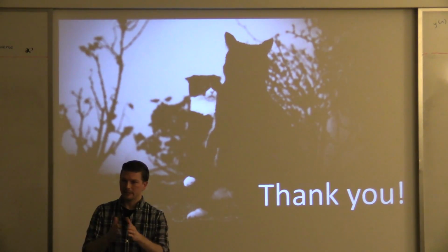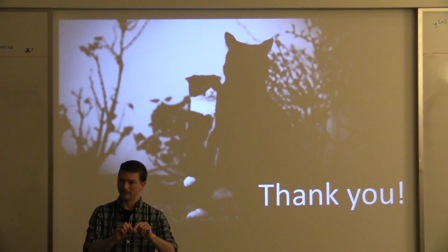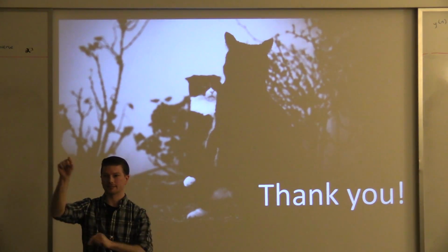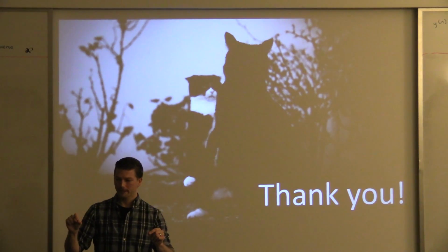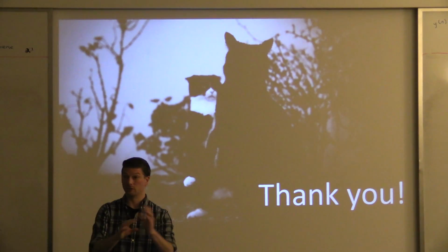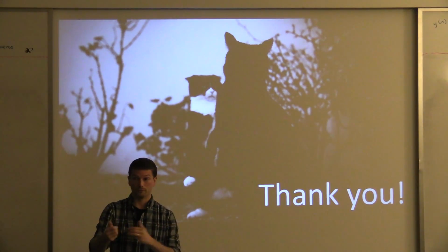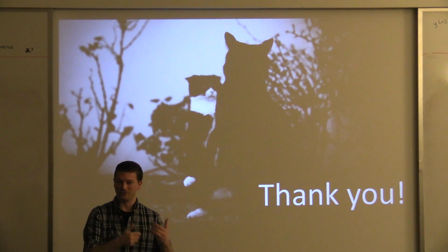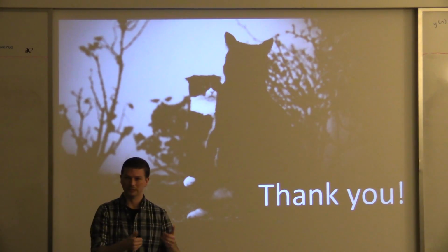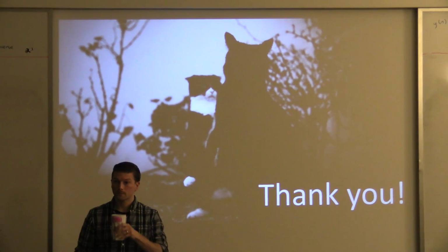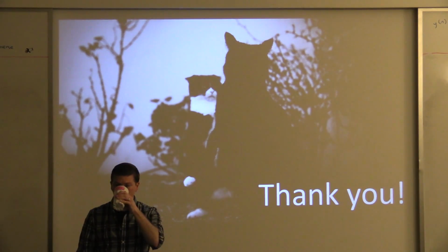So rather than making the equalizer longer, we say let's not be so stringent about putting zeros exactly here. You can choose whatever solution you like in that solution space, providing everything after the relaxation window has been squashed down, but everything within the relaxation window you can do whatever you like. So it gives you more freedom. And the optimization criteria, when you solve that, will intrinsically give you the solution that's got the least norm, the smallest norm. And the relaxation window basically blanks out the early reflections to some extent?